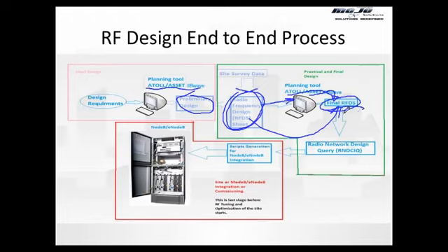RFDS is radio frequency design sheet. Once the RFDS is prepared, that's the second last step in the domain of RF engineering. But RFDS basically contains site information, azimuth, height, all those details. It contains what kind of Node B we will be using, what antenna we will be using, what kind of remote electrical tilts we will be having.